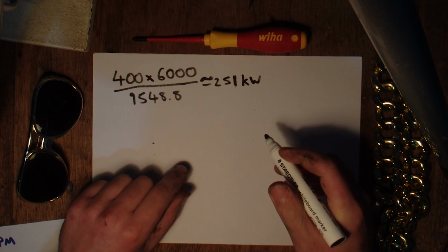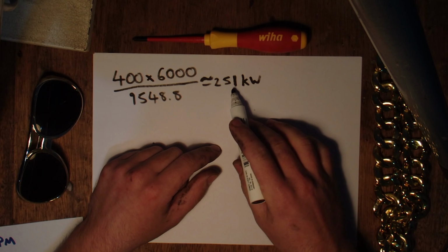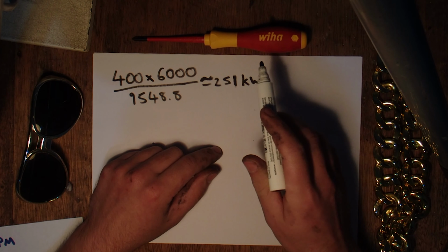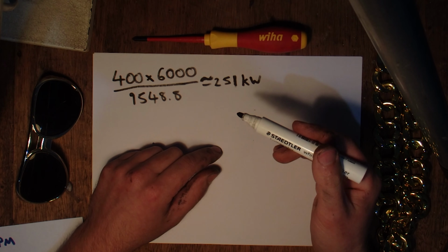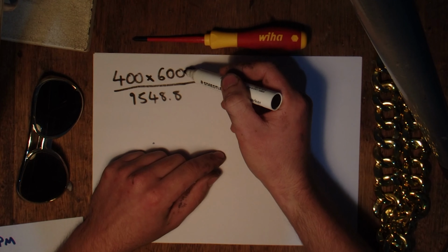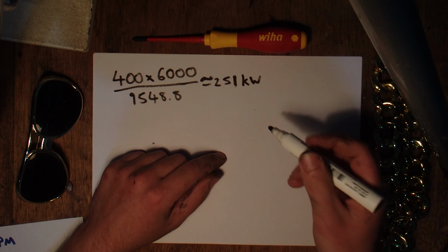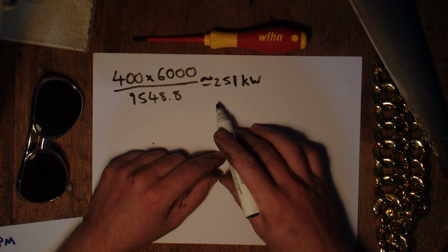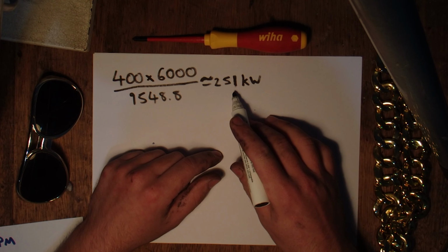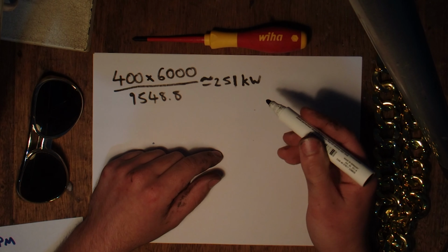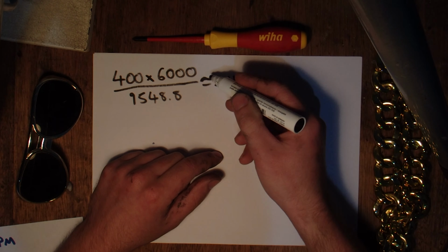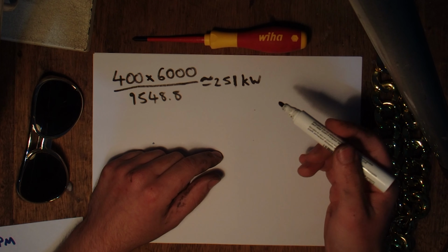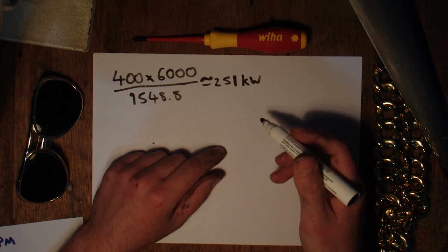Cool. And so that's how much power you're making, and that's going to be the force accelerating the car. So you may have experienced before, if you increase the RPMs in your car, then it feels like you push back into the seat harder. So this torque and the increase in frequency gives you more power, more push. So kilowatts is push, and it'll also allow you to maintain a higher speed. So if you want to either increase the speed or maintain a high speed, then you want to make more power. So you're going to want more RPM out of your engine, depending on the characteristics of it. If it's not making any more power because you're just spinning it too hard, then don't do that either. That's not going to win for you.